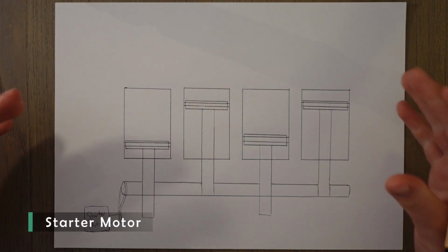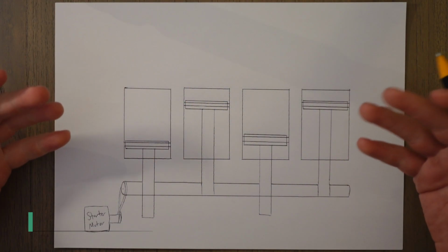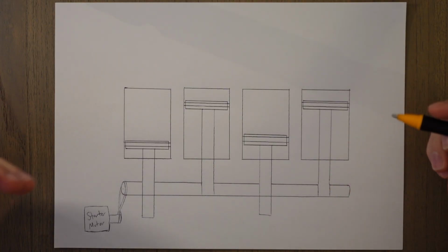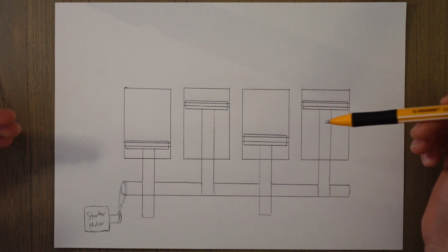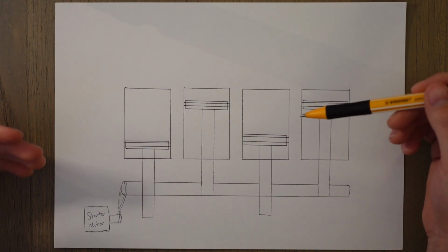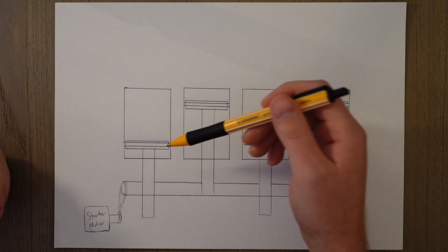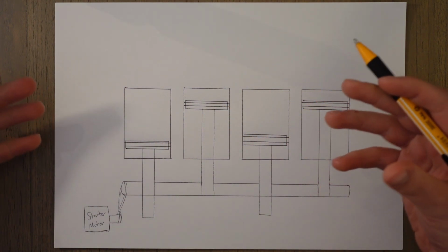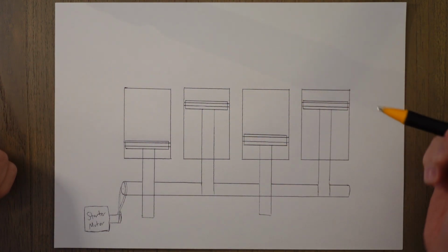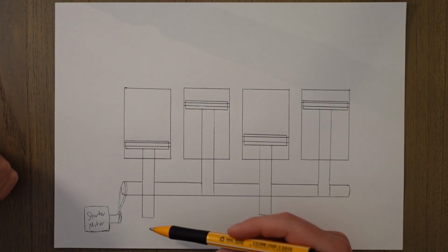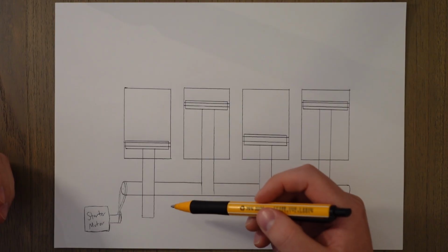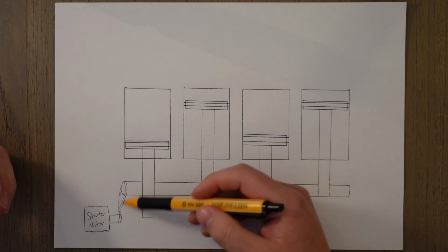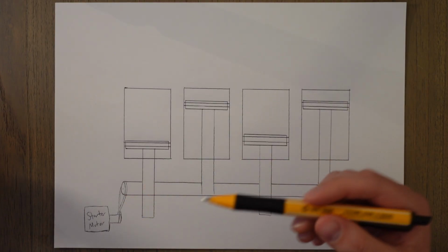The 4-stroke cycle is just what it says, it's a cycle, so it's quite hard to define a start point. So we can't just step in at any one stage of the cycle to kick it off. Each of the steps relies on the previous one. So how do we make the engine kick into life then? Well, that's where the starter motor comes in. This is a small external electric motor that is connected to the engine via the gearbox, or in this case a belt or maybe even a chain.